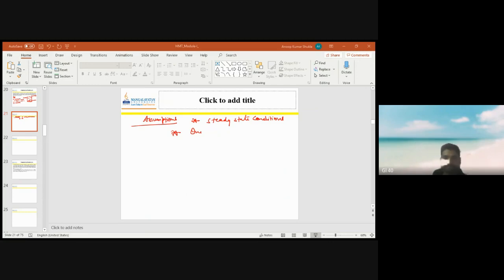And what amount of heat is flown by this electric wire to this tube, we can calculate simply by Q equal to V into I, voltage into current. 3.6 volt is given, current is 0.5, so ultimately 1.8 watt is given, and this amount of heat we can quantify as flowing readily outward, we are assuming.